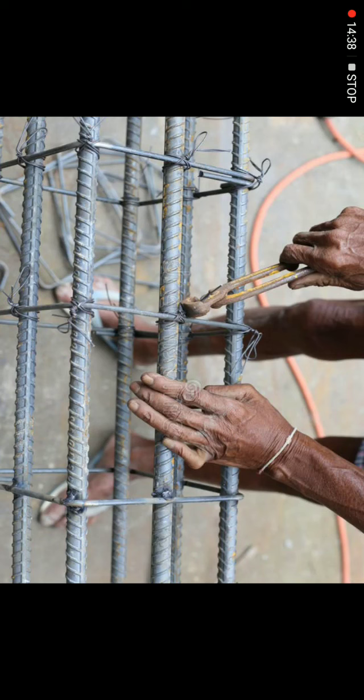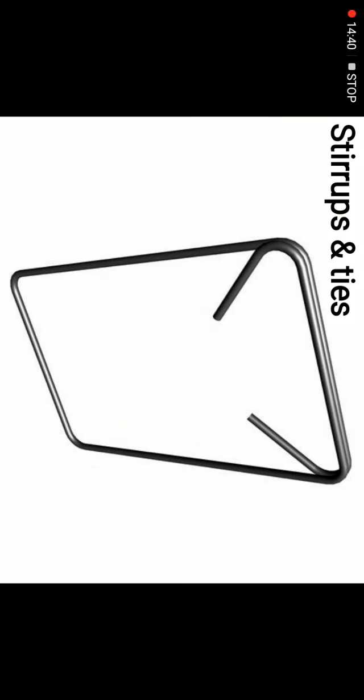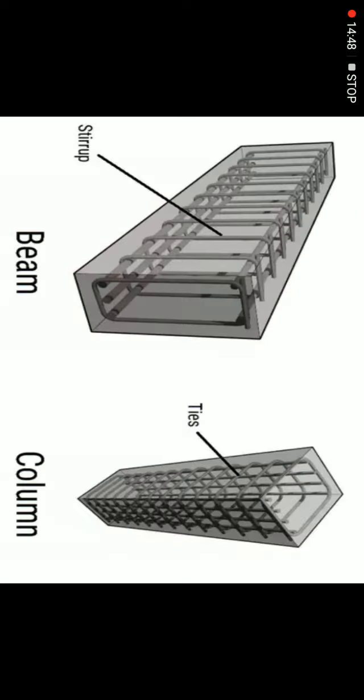Okay, this is the arrangement of reinforcement. This is the stirrup shape. Normally 8 mm dia bars are used in beams. This is the beam column reinforcement. See, the bottom reinforcement is tensile reinforcement in a beam. The top reinforcement is also called compression reinforcement or hanger bar.